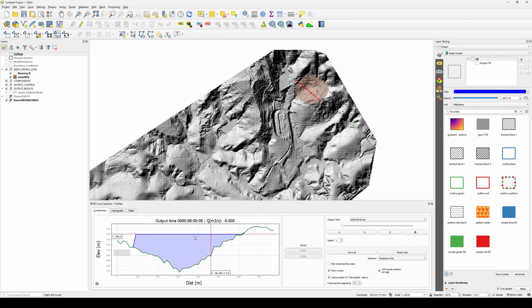It's just going to show me, you see how we have the volume here at 940 meters. It's a completely flat surface across the entire surface. This would not be the case with the raster. In the raster, you will see the differences in elevation. So this can have a lot more volume than the actual terrain would have. So this is just another way of seeing that.